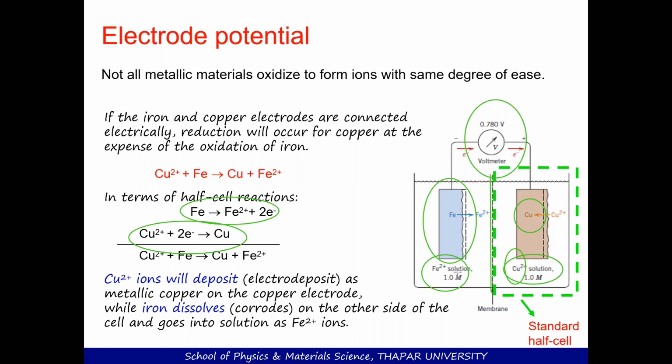In the half cell where there is iron, Fe from the metal sheet gets oxidized and goes into the solution. So you have ions coming from the sheet into the solution, and the two electrons that are liberated are transferred through the external circuit from iron to the copper.